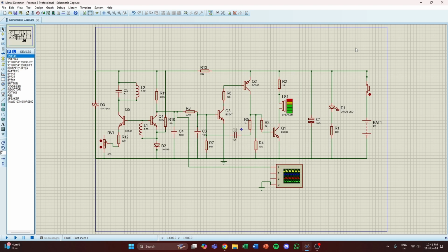The signal on the collector will be a waveform, but this is smoothed by the C4 capacitor. As the resistance of the pot is increased, the voltage on the emitter will increase and the base to emitter voltage will be less, so the transistor will not be turned on as much.